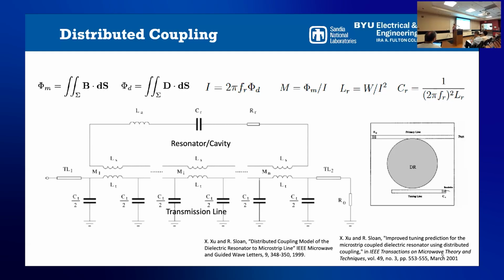Different components within that loop represent how energy from that eigenmode can couple onto different parts of the wire. In order to get the parameters they need to do this, these authors did a full wave simulation of their geometry and then integrated along certain flux planes in order to get the parameters they needed for the circuit simulation.